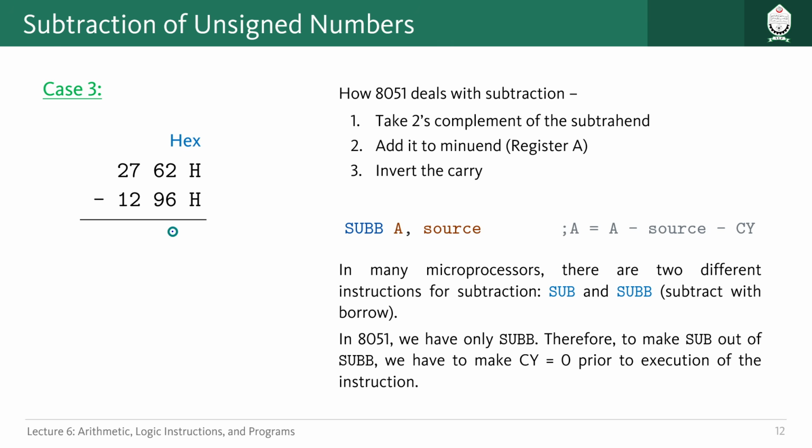Let us try to understand the same concept for 16-bit numbers. So for 16-bit numbers, if I want to subtract here, you see the same value actually. Just like before, the first 8-bit two values are 62 and 96. So here also the result should be CCH. But here also, because 6 is less than 9, we had taken some borrow from the next stage.